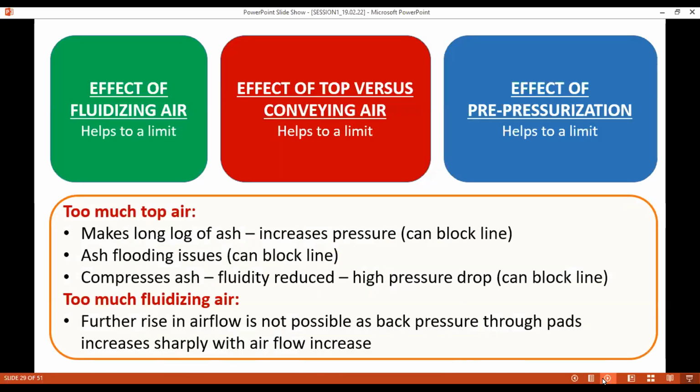What we have seen in our experience of those 40 different ash samples, of course, they behave a little differently. And if you increase the fluidization air, you generally get a very good increment in the tonnage. But there is a particular limit. Beyond a certain limit, you don't get that increment, but it doesn't decrease either. It remains there, stabilizes. But if you go from no fluidization to some fluidization, say 5%, there's a huge positive impact that you can make to your system.